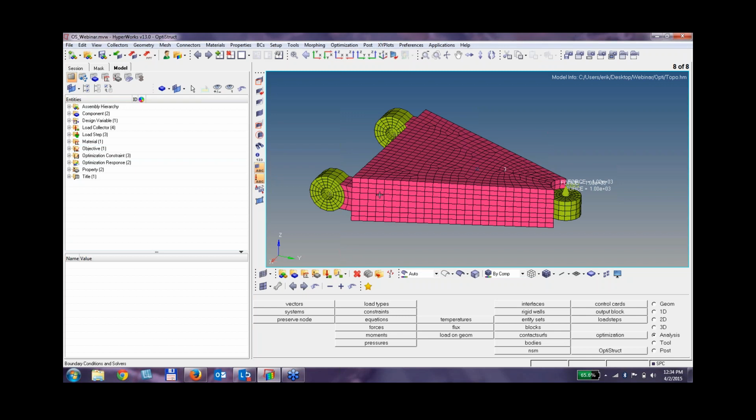So in inertia relief, even though I'm really not counting on the inertia of this part, it doesn't have a tremendous amount of it, especially in regards to the amount of force going into it, the inertia relief analysis works by preventing rigid body motion. It will figure out what the net sum of the forces are, and allow the part to deform accordingly. So that's all I had talked about in regards to the control arm and the inertia relief.